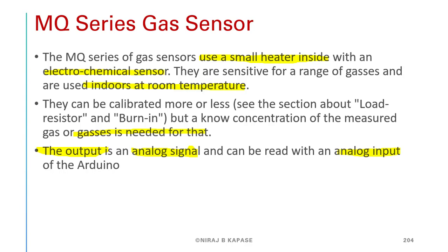While connecting this MQ series of gas sensors with a Raspberry Pi, you need to use an ADC hat on the Raspberry Pi, because the Raspberry Pi does not have an ADC inside it. So we need to use the ADC hat for the Raspberry Pi as well.